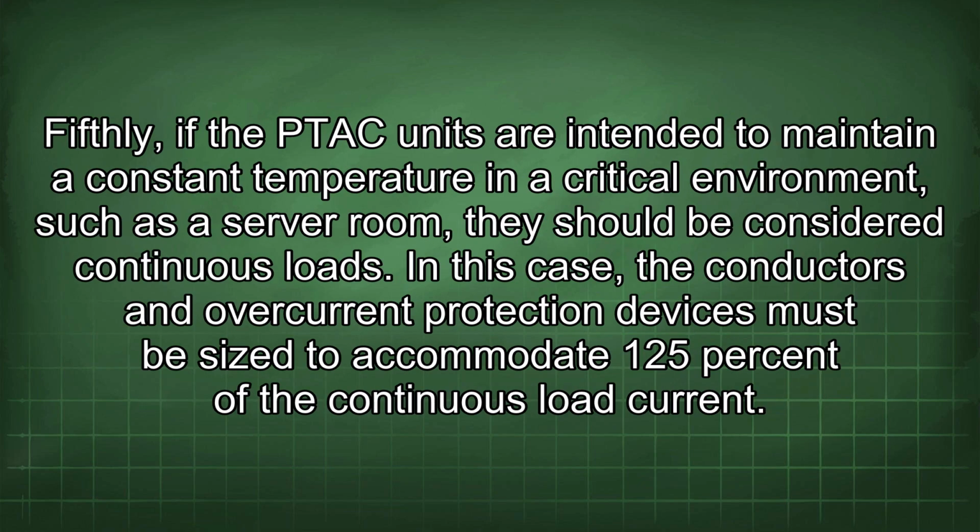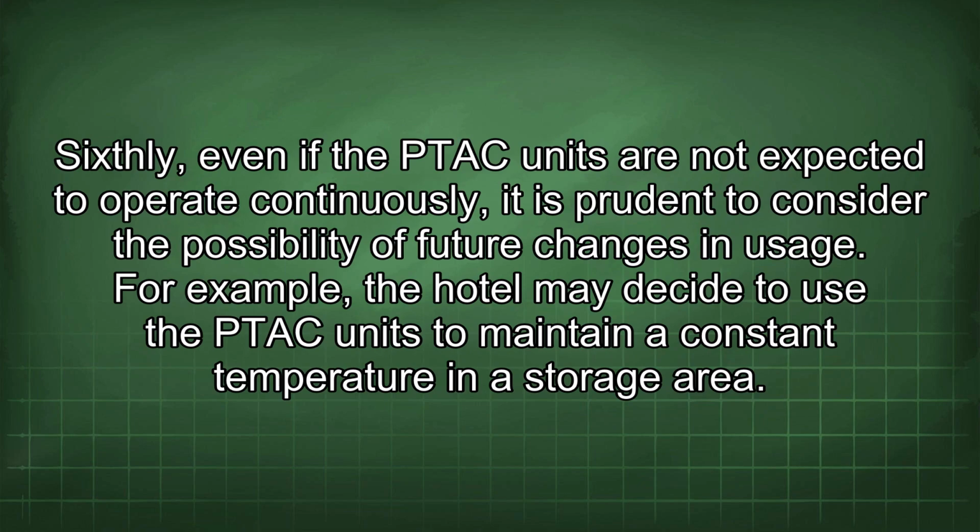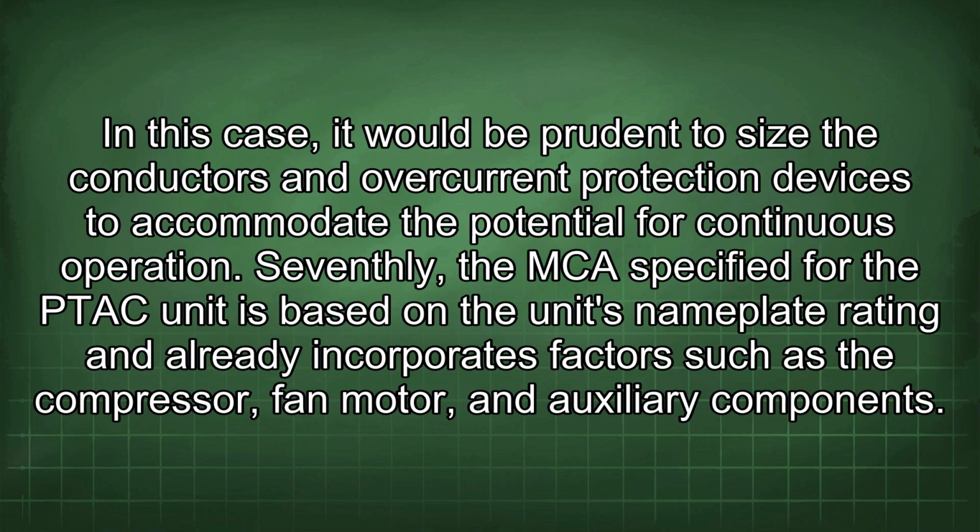Fifthly, if the TAC units are intended to maintain a constant temperature in a critical environment, such as a server room, they should be considered continuous loads. In this case, the conductors and overcurrent protection devices must be sized to accommodate 125% of the continuous load current. Sixthly, even if the TAC units are not expected to operate continuously, it is prudent to consider the possibility of future changes in usage. For example, the hotel may decide to use the TAC units to maintain a constant temperature in a storage area. In this case, it would be prudent to size the conductors and overcurrent protection devices to accommodate the potential for continuous operation.